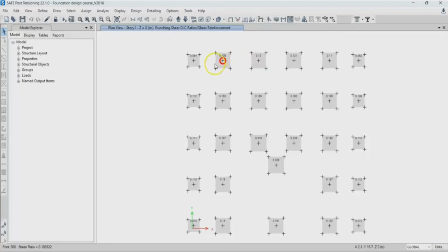So meaning our footing can also, let's say, if we provided a footing thickness of like 400 millimeter, we can reduce this thickness, right? So let's say 300 millimeter, but you need to go with a minimum of 250 millimeter, because you cannot reduce your thickness to the extent that the thickness of your footing is so thin. You will need at least some considerable amount of thickness. But we can reduce this to 300 millimeter.